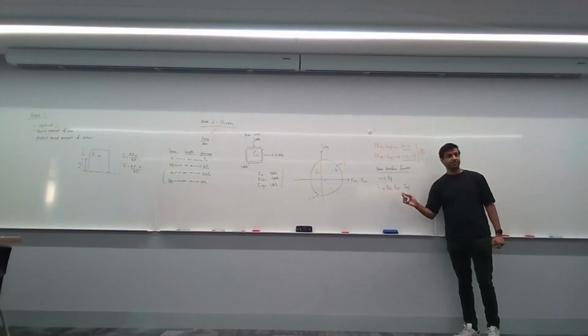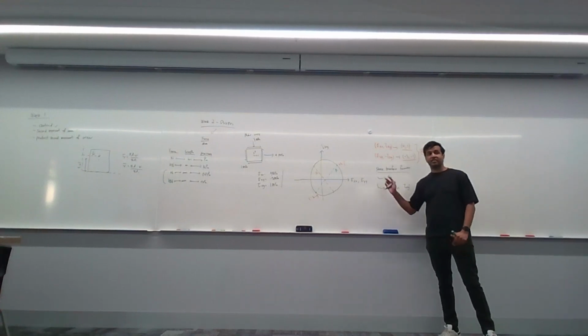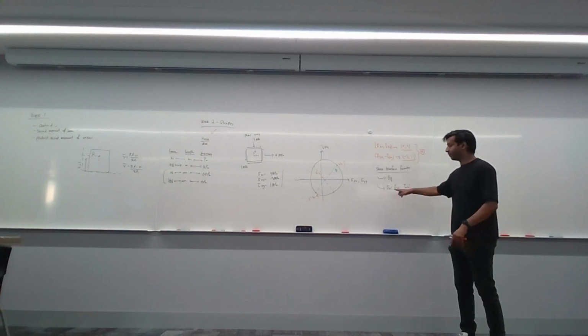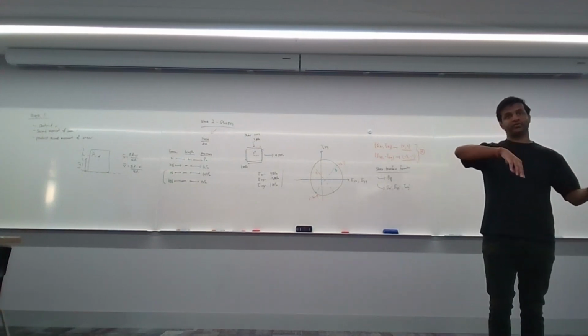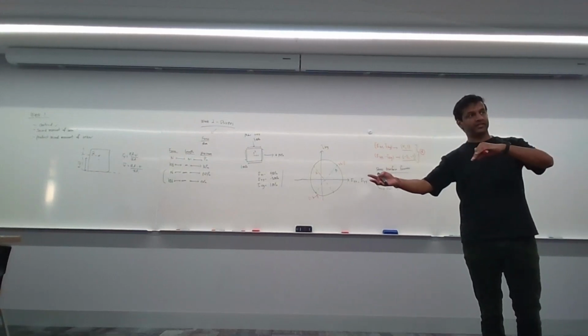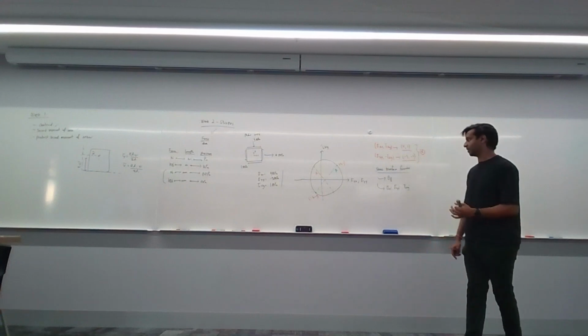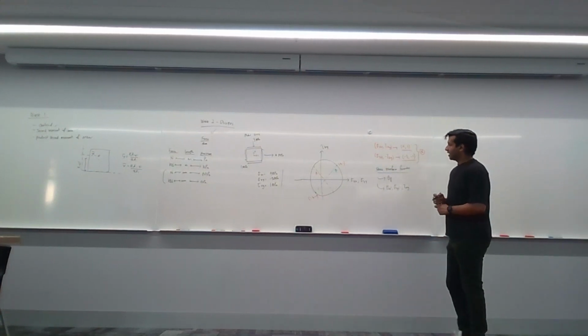These are formulas which are in your notes using any given theta. It doesn't have to be theta p, it can be any theta, any angle you wish. These formulas will help you transform the original sigma x-axis to the new sigma xx, or yy or tau xy, whichever you want to call it. Okay, so those are your stress transform formulas that you've got to keep in mind.